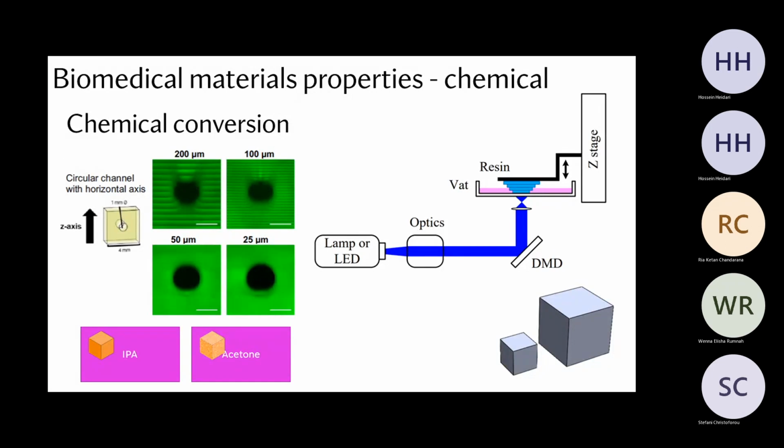The IPA plays a role there. The washes that you do in IPA to remove the residues, the uncured material, that helps, because the uncured material around it is going to block light penetrating in. And apart from that, I just explained how far the light from the yellow box can penetrate the walls of the object. I said just about half to 1 millimeter.